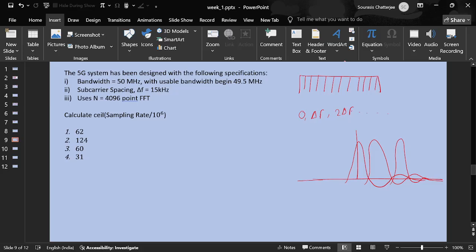I can implement this thing in analog domain also, right? What I am trying to mean is that I have these signals x0, x1 up to xm, and then I do some kind of serial to parallel processing so that I can have all of them in parallel, x0, x1 up to xm, and then I just modulate different subcarriers over them, as you just said.